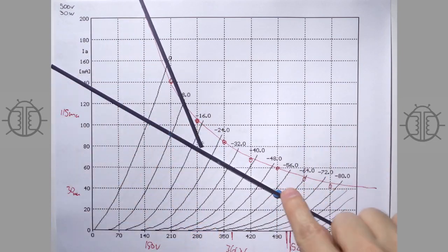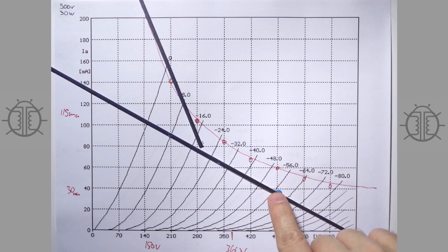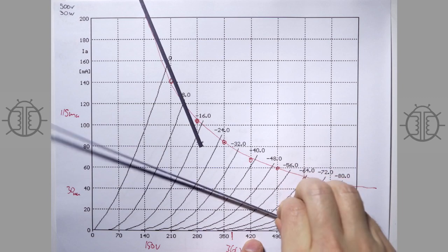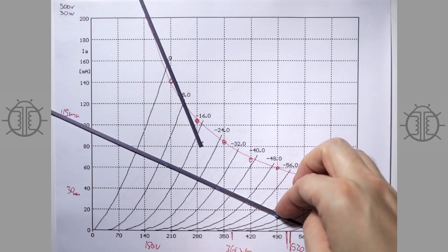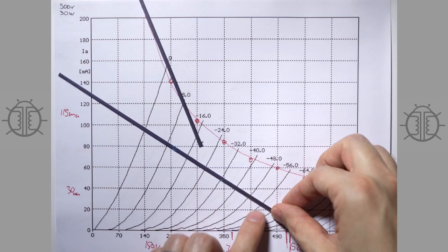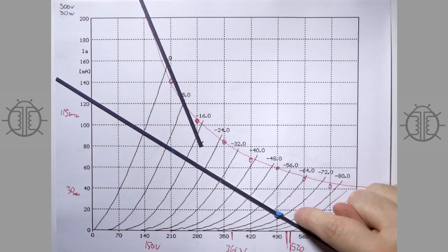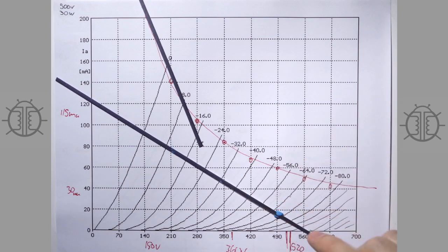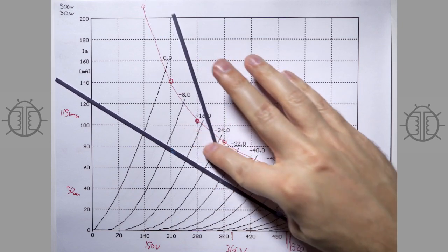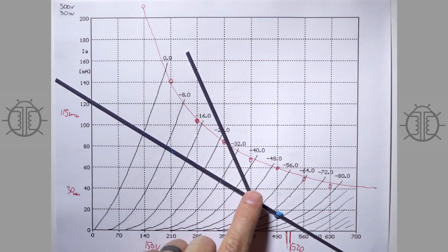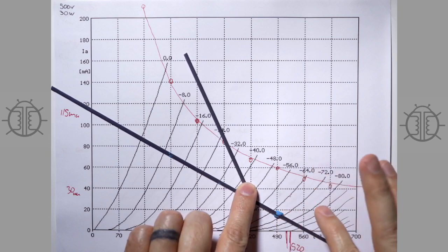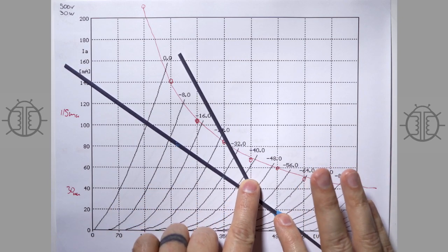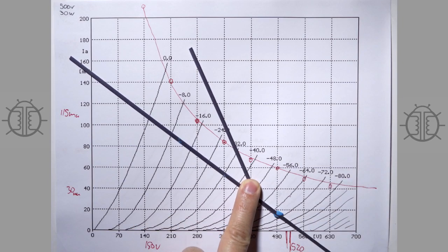The other thing is that if you bias the amp differently, like let's say you take your DC operating point and move it down here, which a lot of AB amps are biased kind of cool, which is totally fine. But look now we can only go up, what, 1, 2, a couple of divisions. So now the other tube is turning off here, right? And so if our load drops, we're ending up with load lines that kind of start doing this kind of thing, like this.